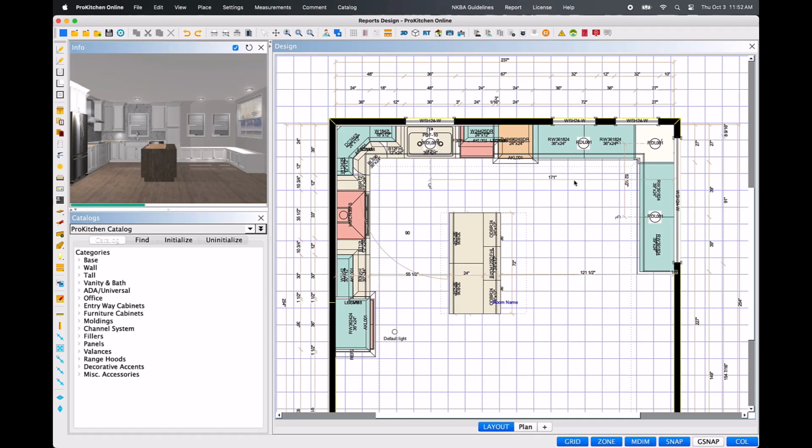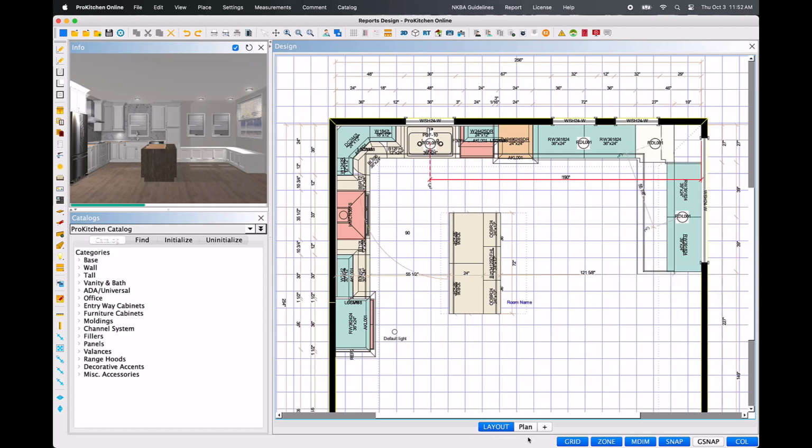Point to Line is also a dynamic dimensional line and can be adjusted to fit your design requirements. But remember, with the dynamic dimensional tools, the last thing that you touch will be the item that moves when you alter the dimension line. So moving items to their centerline placement in relation to a wall may not work out quite so well. Because when I change the dimension as demonstrated earlier, the wall at the end of the dimension line will be what moves, and will inadvertently alter the length of the wall my item is sitting against.